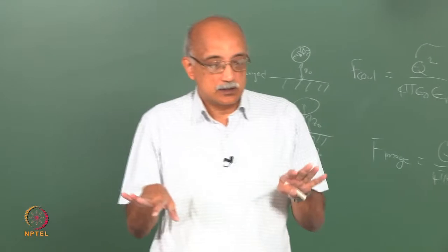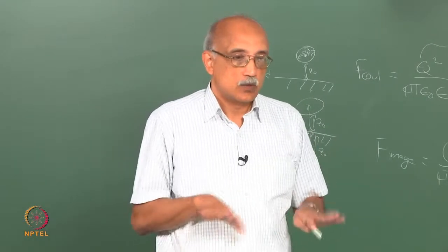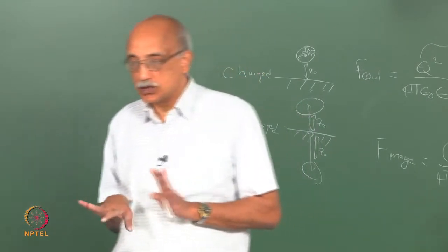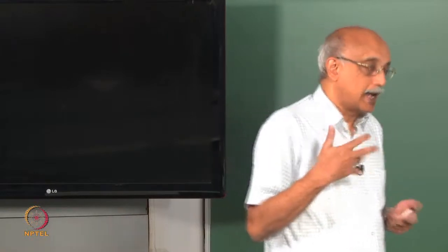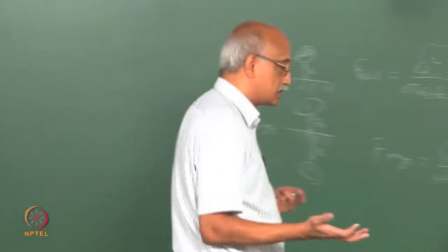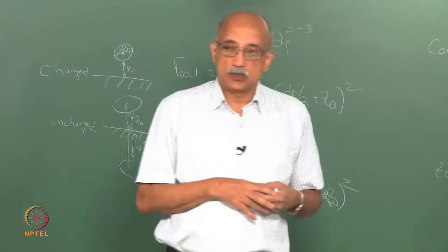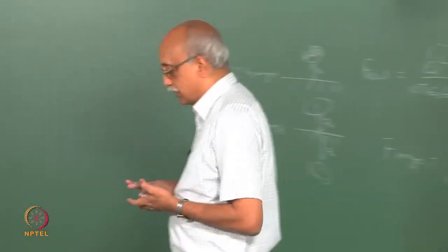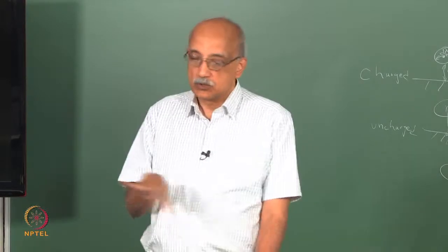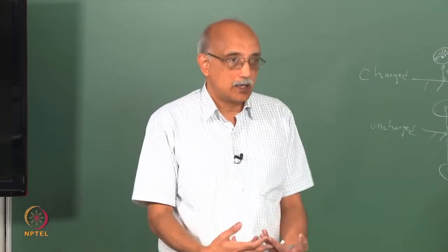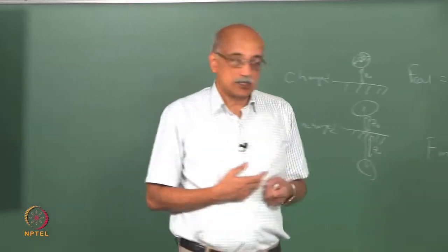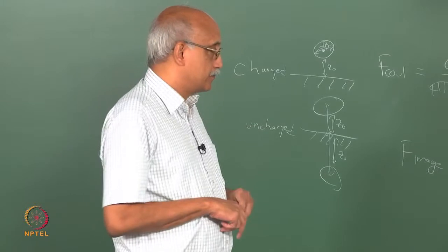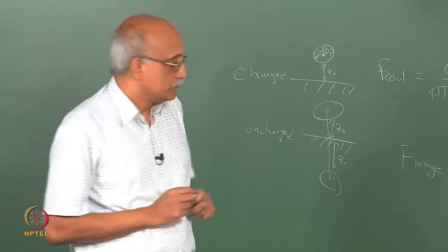And sometimes these can be conflicting effects, because what you really ideally want is a slurry that has high attraction to the surface but low attraction to each other. And part of the challenge of designing a polishing slurry is to achieve this. How do you maximize the affinity of the particle to the surface that you are trying to polish while minimizing the affinity of the slurry particles to each other? And again, the zeta potential is a mechanism by which we can accomplish that.